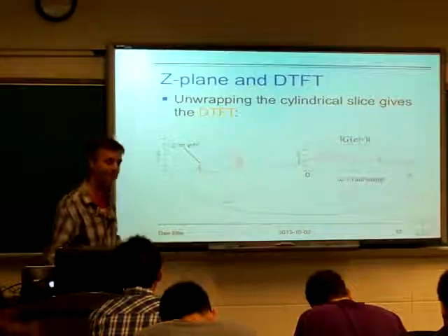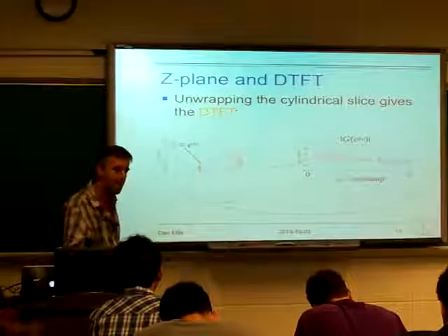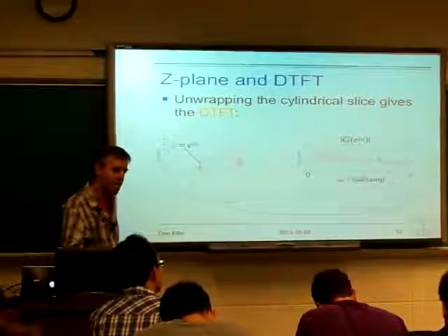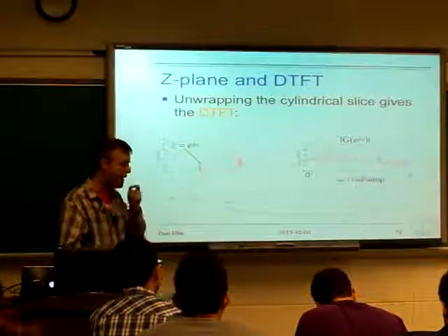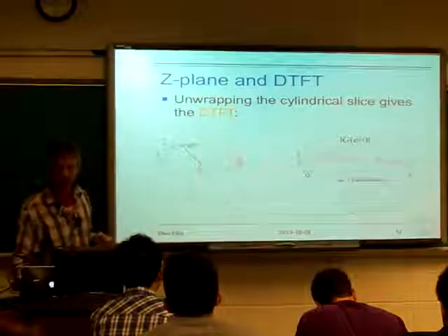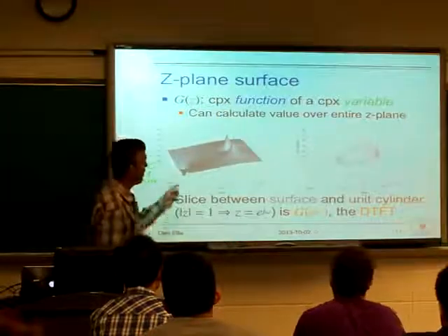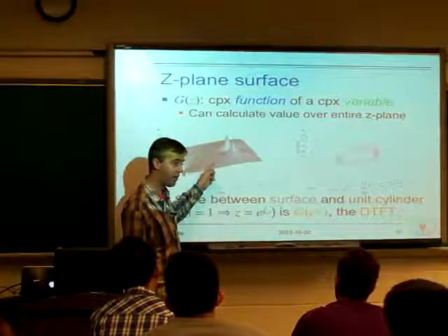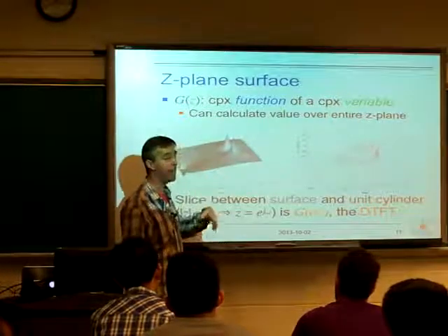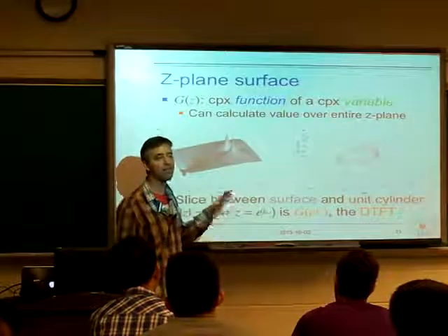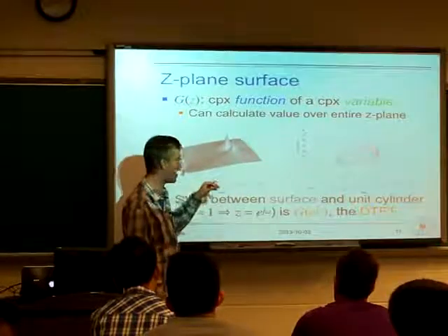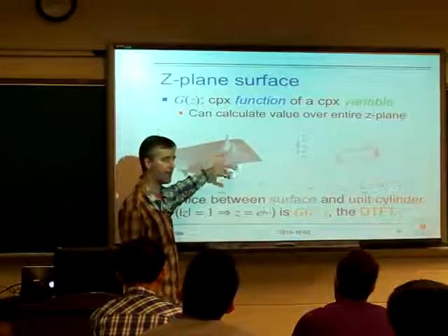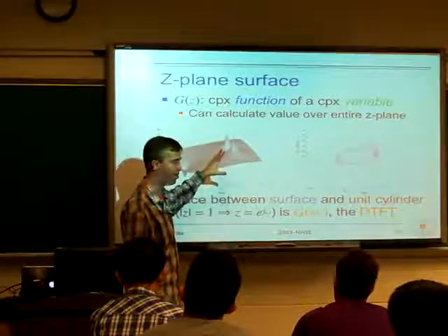Yeah. So basically, this correlation between Z transform and the FT. So this is basically done only in the region of convergence. Right. So that's a good point. Thank you. So here, see what I've done here. I've plotted the x of z, the closed form expression, for all values of z, and the region of convergence has been forgotten. I've just said there's no actual sequence that has a Z transform that can take on this form. I've stated that. I haven't proved it, but it's true.